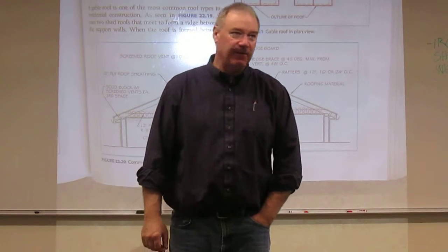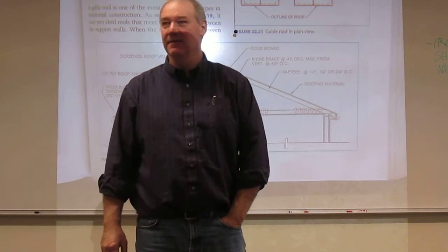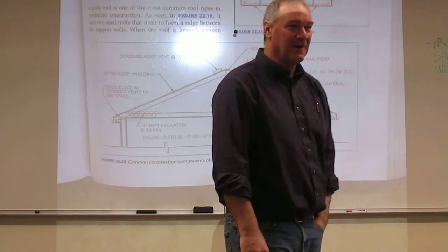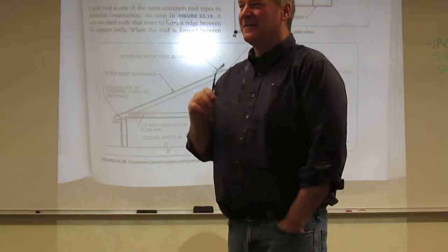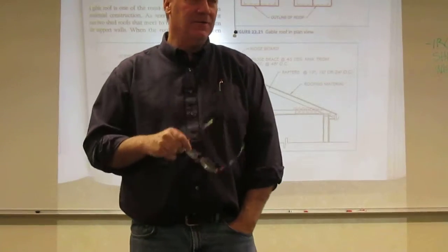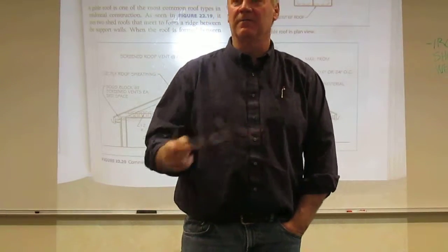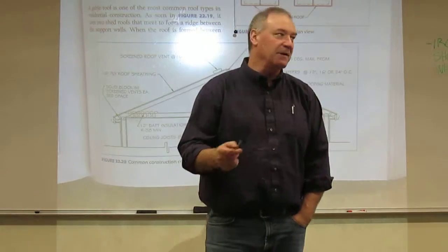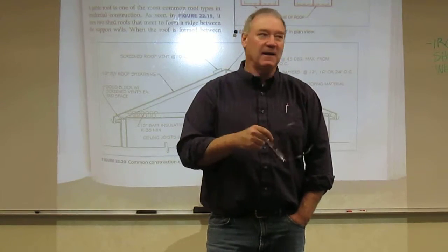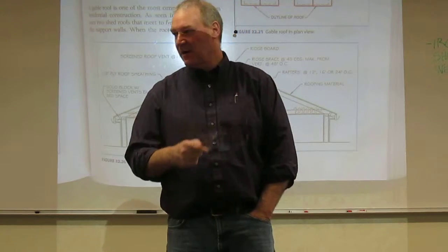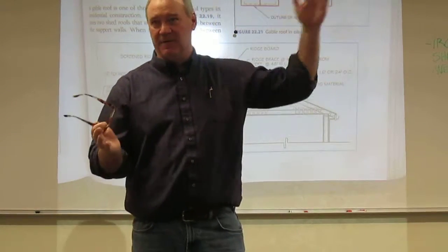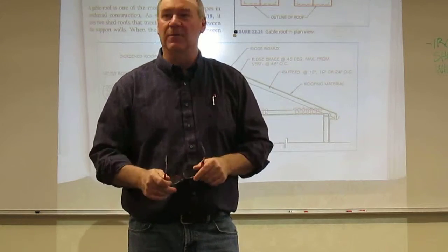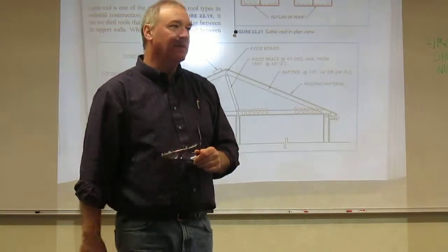Roofers, by the way, have the most dangerous occupation in America. They are not susceptible to OSHA on a 7/12 or below. If you get to an 8/12, now they have to have fall protection, they've got to have guards while they build it, and all of that kicks in. So your 8/12s and above generally get a little more expensive because they're going to cost more to build.